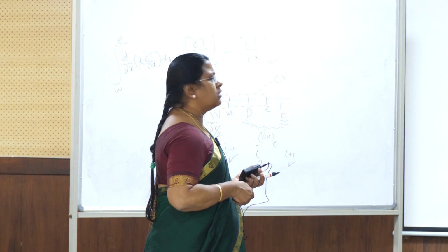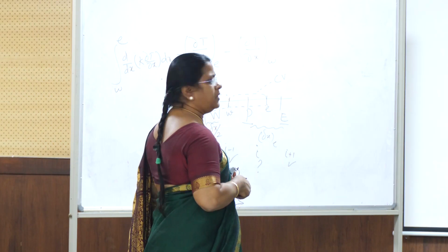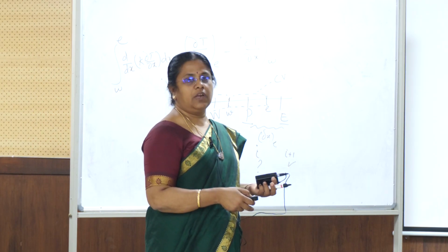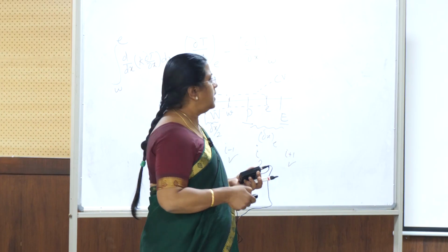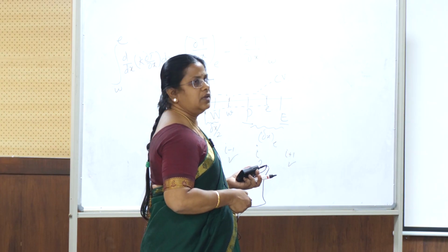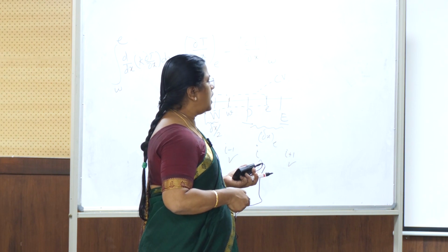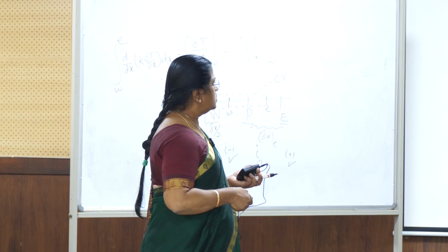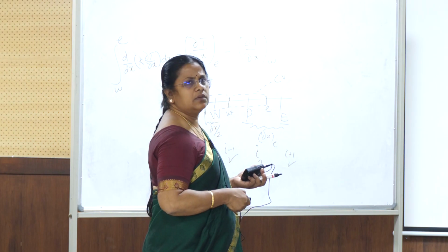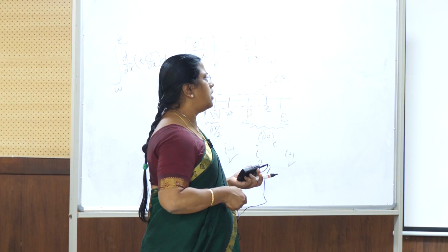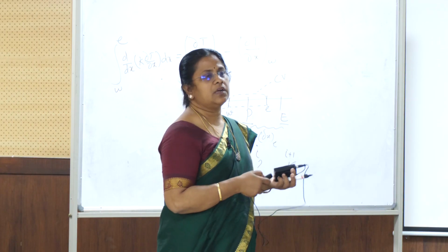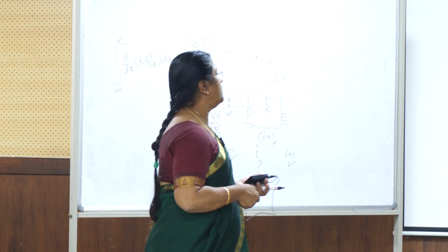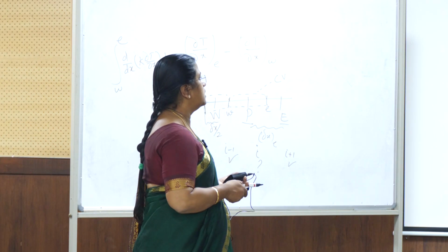To find out, we want to calculate the temperature at the point P. So we have the previous iterated value and the current iterated value. How much should we consider? Based on the alpha value, you can consider that. If I put alpha equals 1, what will happen here? Both will get cancelled out, so only the current value is in. You will take the current one. If alpha equals half, then half of the previous iterated values you will take, and half of the current value. So based on this alpha value we are considering that.